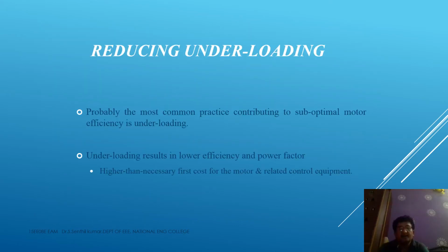If the motor runs under loading, surely it is going to affect the performance of the motor. So care should be taken while choosing the size and rating of the motor. The load side calculation should be done carefully, and we should ensure that most of the time the motor does not run under loaded, because if the motor runs under loaded for a prolonged period, surely it is going to affect the motor performance.